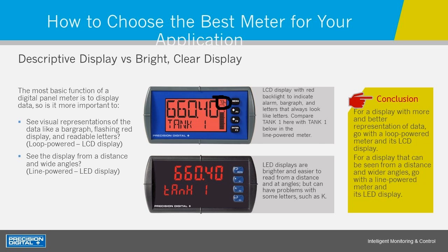But now we've also got this percentage that's displaying in the upper right, which is relatively small and difficult to duplicate on something like the ProView on the bottom. And you've got this 20-segment bar graph here. So when I look at this meter on the top now, I know what my tank height is or my number of gallons is. I've got a label here to tell me what I'm looking at. I have a bar graph, so intuitively I just know where my level in this tank is going to be. I've got a percentage being displayed on there. That's a lot of information, and it's very clear and intuitive.